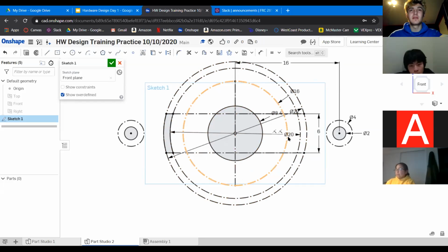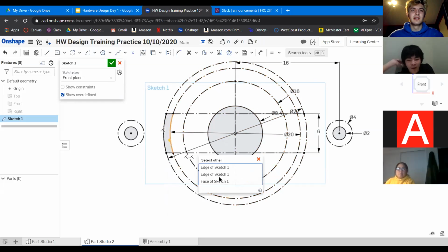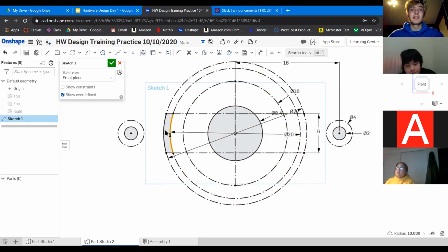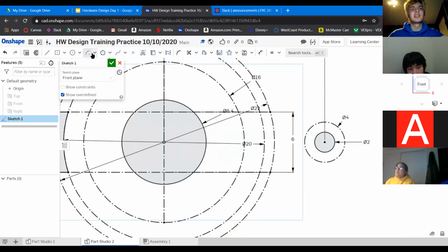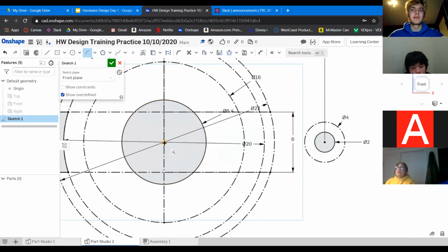That would be a bit of a pain because I kind of have to select the real, the defined line, which is underneath the construction line. So I would have to go in here and then select other, and then select that spot for each different selection. So I'm just going to do the same thing on the other side, which is okay because I'm not actually making any dimensions. It's still constraints. It's just not a mirror.